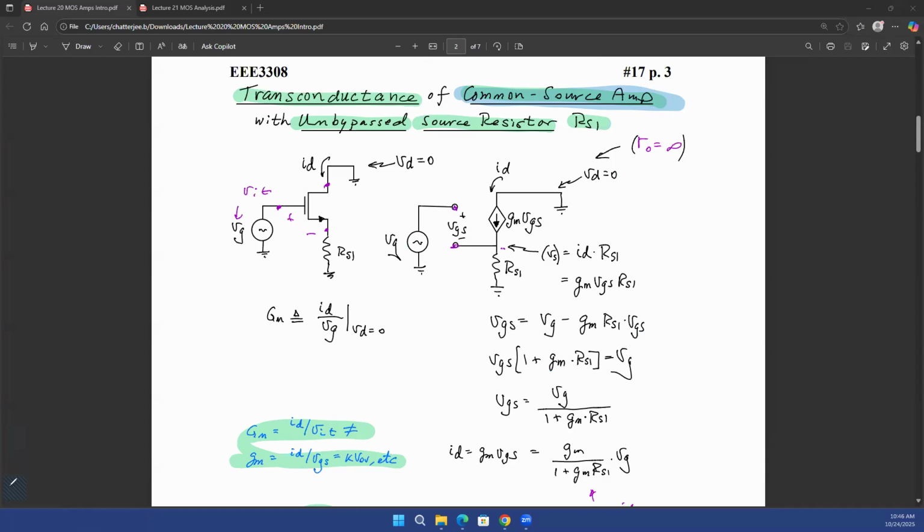Okay, so this was the first example that we had taken a look at in the last part of last lecture. If you have a MOSFET, you know that the AC small signal model of the MOSFET might look something like this on the right hand side. You have a VGS, a gate to source voltage. Gm times that VGS will give you the output current of the MOSFET.